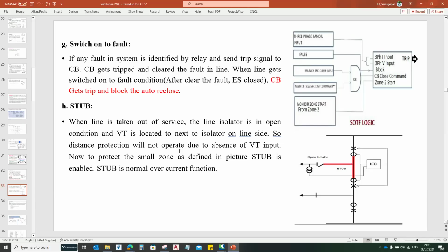to energize the circuit breaker, in that case you have to ensure that all the air switches you closed during the tripping condition should be open before energizing the circuit breaker as well as the line.